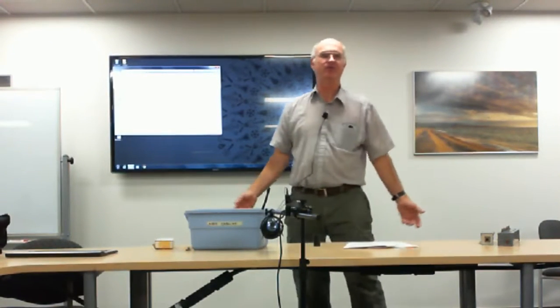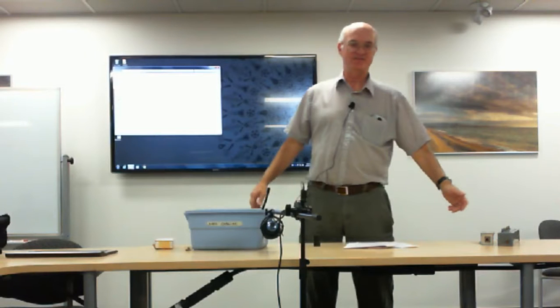The capture effect is great when it's used properly because FM is so quiet. You get the signal in there, it grabs it, and holds it nice and clean. But when you've got two signals competing and they're close in frequency, the capture effect can come back and bite you. So receiver overload in FM can be a real problem. But it can happen in any mode.